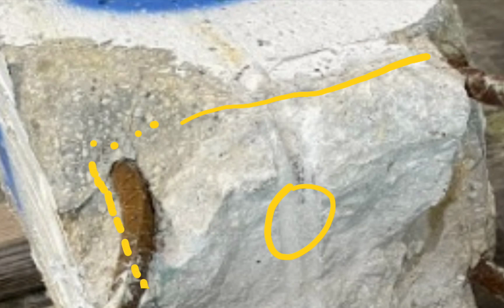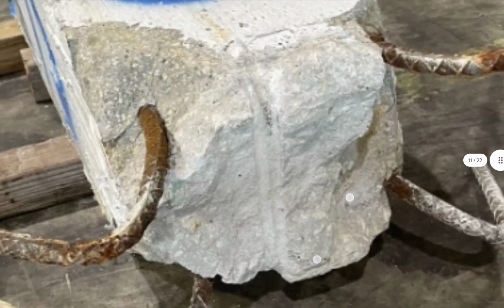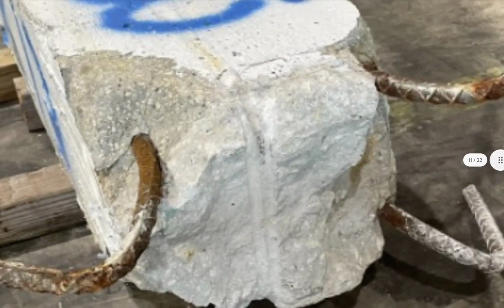And I know this looks like it's dropping off. It's not. This concrete spall is dropping off. So's that one. And then this one comes around it like that. You could measure and see the quality and fit and finish, how great they were doing this. You could then explore how deep this is, even though I know that it's deep enough that it held on, that it spalled the concrete. That was not the failure of that.